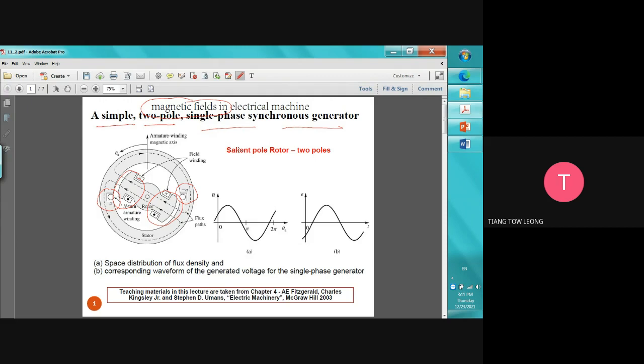If you still remember from the beginning, I told you that this subject would be a little bit different, in that we're dealing with material, and also space, or geometry. Space means we need to know how good the flux going from the rotor to the stator, crossing, and then coming back is. So we need to know how good the magnetic flux density in the air gap is. The more the merrier, but too much creates unwanted torque or unwanted power.